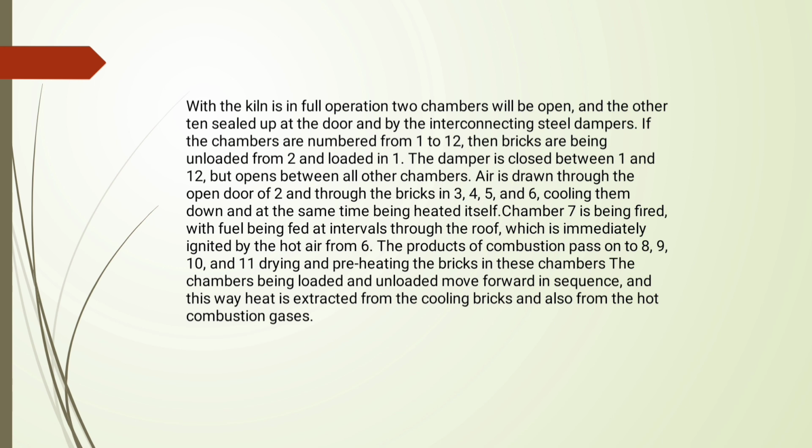The products of combustion pass on to 8, 9, 10 and 11, drying and preheating the bricks in these chambers. The chambers being loaded and unloaded move forward in sequence, and this way heat is extracted from the cooling bricks and also from the hot combustion gases.